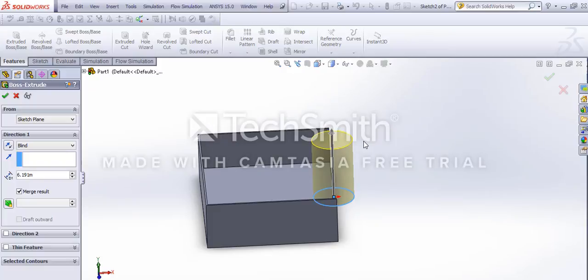The area would be pi r square, pi times r squared, where r is the radius of the circle. And the moment we add the h, the height, it acts as a cylindrical face. But the problem is you cannot draw on cylindrical or irregular faces. You can only make sketches when you have a flat 2D plane.